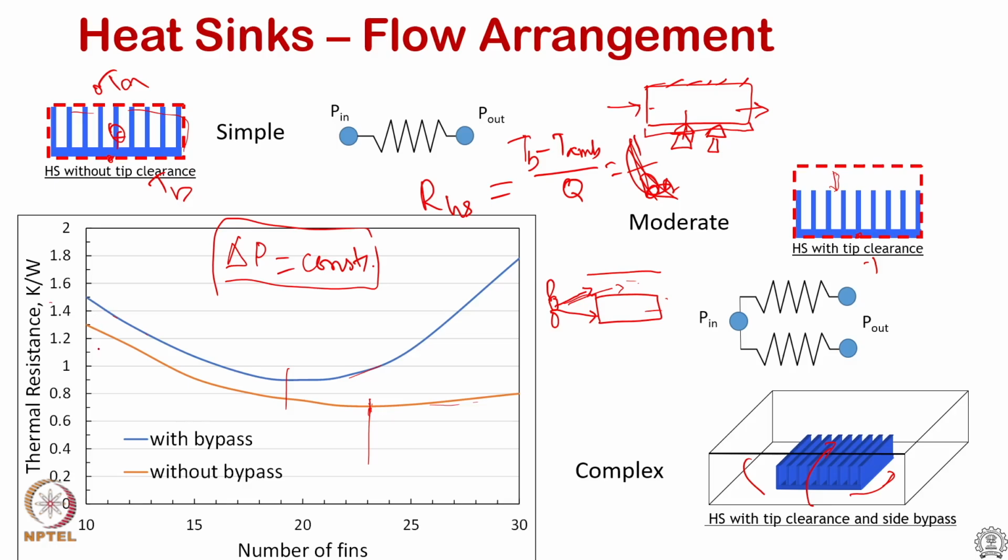So, when there is more flow, heat is dissipated. The mechanism of heat dissipation is that heat is conducted through the fins and then convectively transferred to the moving air that is going between the fins. As the air is flowing through the channels of the heat sink, it picks up heat.